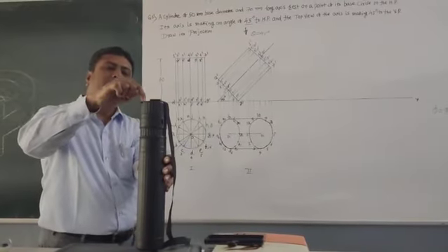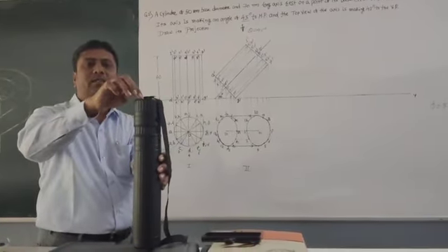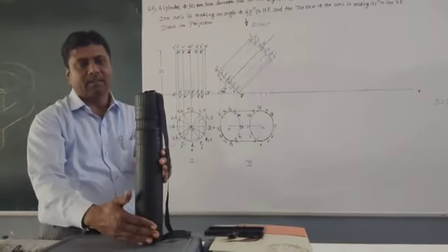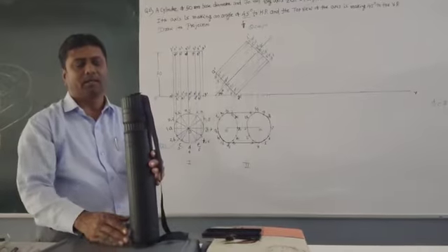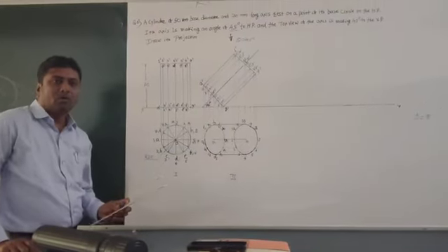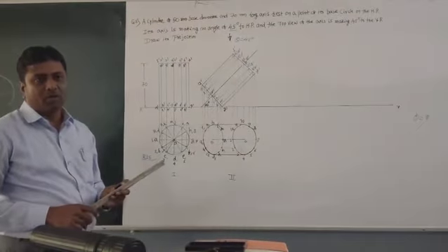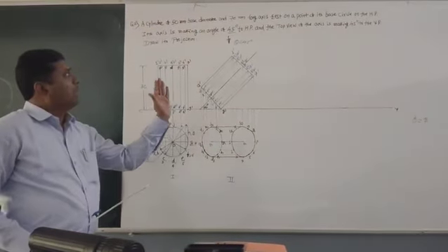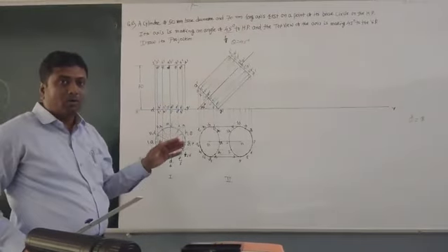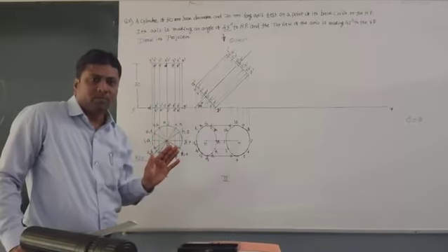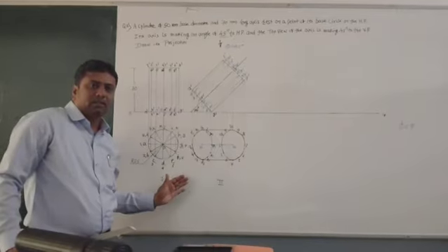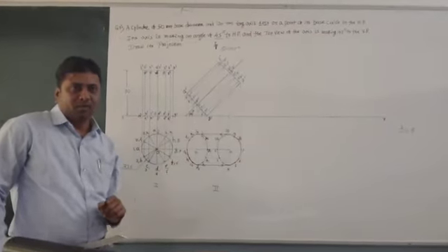You get the top view as a circle. And what is the front view? You get this space, and this is nothing but a rectangle. So first you have to draw the top view and front view, as per the condition given in the question, of the cylinder. Now this problem you can solve in three stages: stage 1, stage 2 and stage 3.